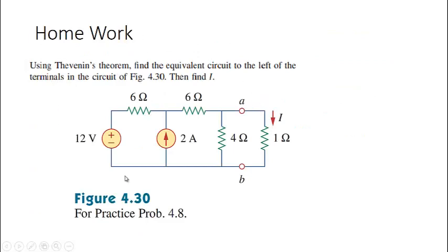So please try this. This is a similar problem. You can calculate the value of I by using the Thevenin theorem. Simply disconnect this load from it and calculate RTH between these 2 points. That will be series, and this is open circuit, this is short circuited. Series combination of these two, and then the combination of these two will be in parallel with this. That will be RTH. And when you open up this, you have to find out the VTH at this point.